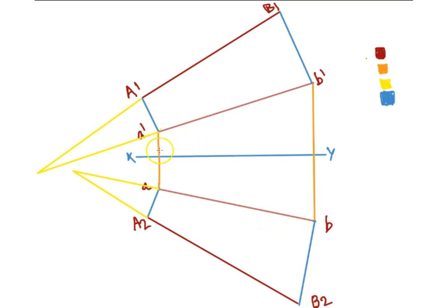The critical thing to know here in the plane rotation method is the method of drawing the true length. How do you draw the true length? Suppose you know one of the projections. If you look at the plane rotation method, we know that this distance will be equal to this distance, and this distance will be equal to this distance. Similarly, this distance will be equal to this distance, and this distance will be equal to this distance.